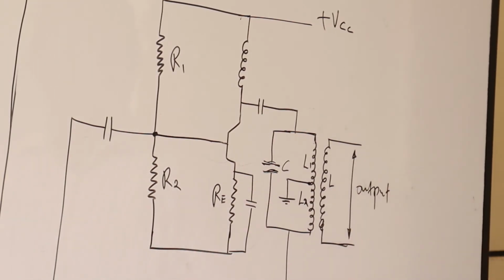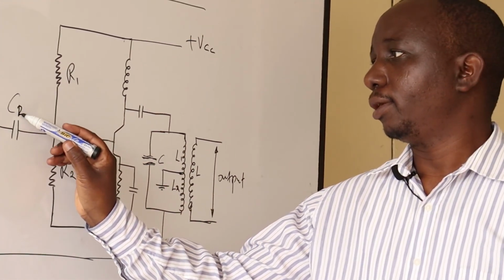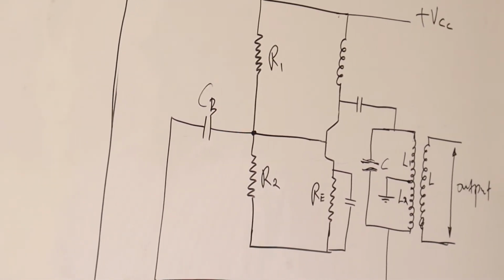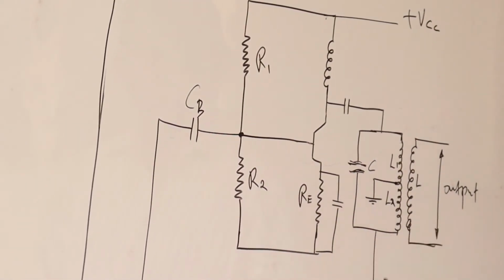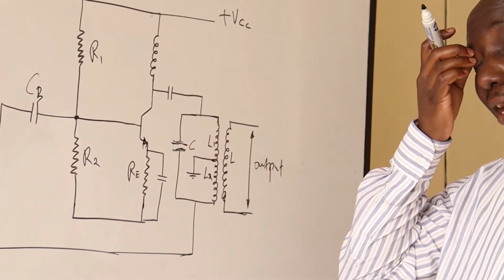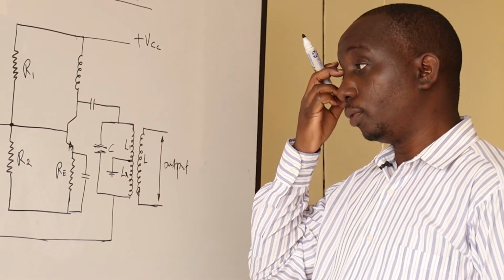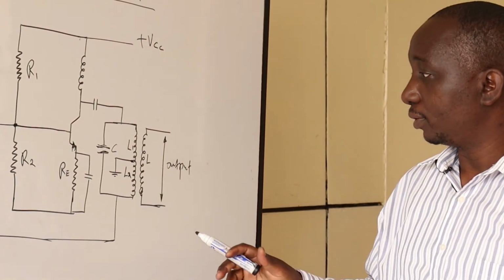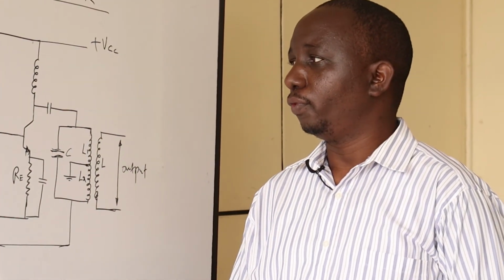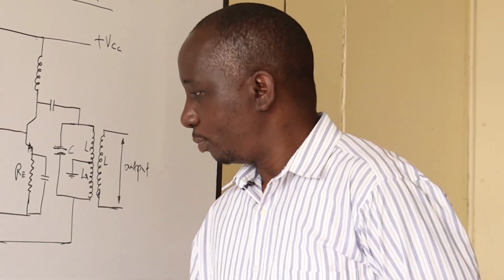It's nearly the same way. We also supply the voltage, and this is the coupling capacitor for the feedback. So once we connect the supply here, the collector current that will be established here will produce oscillations. These oscillations are kept going by the positive feedback that's connected through the capacitor CB. So, operation.